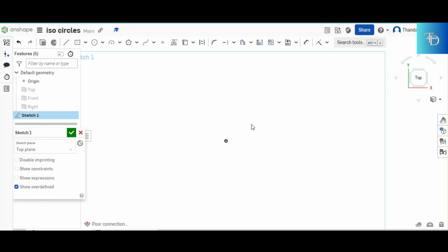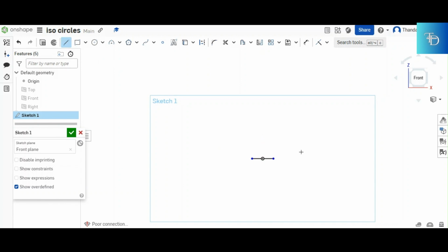Now, when we're dealing with an isometric, you should also keep in mind that everything that you do should be elevated at an angle of 30. So when you're creating an isometric circle, you take your 30-degree angled ruler, you draw a line that goes there at an angle of 30, and then you draw another one that goes in that direction at an angle of 30. From there, that angle should be 30 degrees, and on the side, the same thing applies. The angle should be 30 degrees.